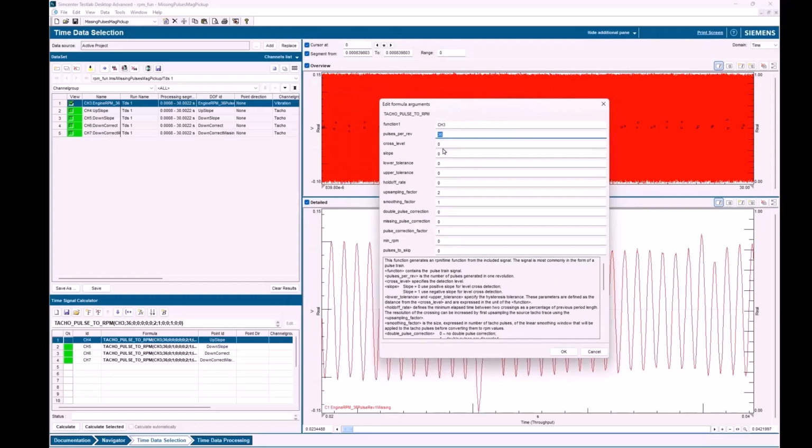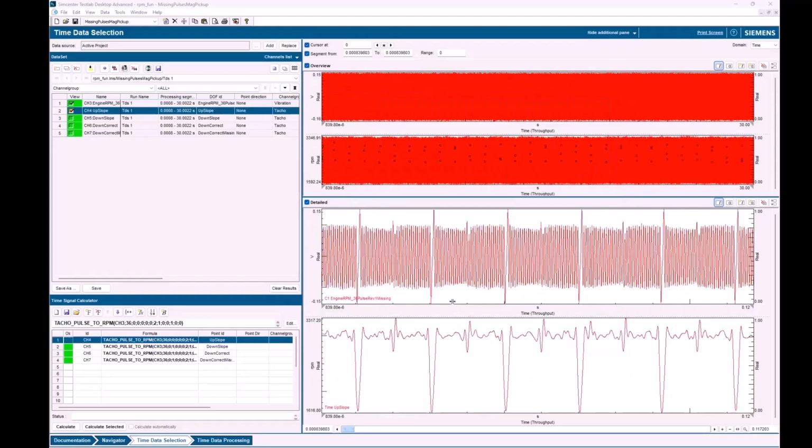And then I do my calculation, put in the numbers, calculate the RPM, and should I be concerned about my RPM calculation here? Yeah, I would be concerned. It's dipping down right where that missing tooth is, because it looks like it's momentarily slowing down, right? Yeah. Because of that large gap.